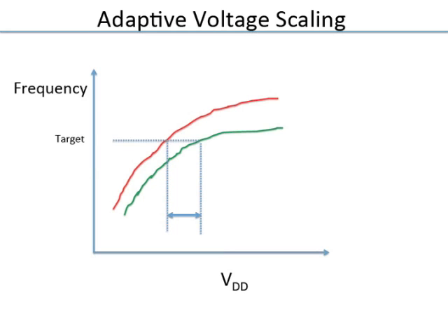Similarly, for a lower frequency of oscillation, you use a different voltage setting. So during testing, you can put in these ring oscillators, measure the frequency, and from there you have an idea of what kind of chip it is, slow chip, fast chip, and so on. Then you come up with this table which relates frequency versus voltage. For that frequency, you look up the table and program the switching regulator to set up that voltage. Okay, that is something which is now commonly done.